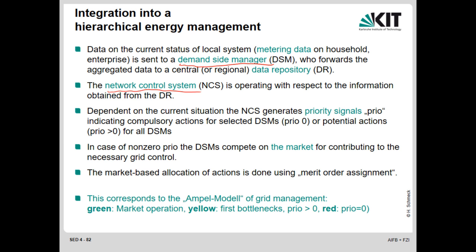A demand side manager needs information on what kind of demand management is necessary in the moment, and what kind of opportunities are on the market to sell a surplus of power or to sell flexibility. And it means that you need a combination of markets, demand side managers, and network control systems, like the distribution system operator, which has to be able to communicate with the demand side manager such that they actually provide the appropriate flexibility whenever it's necessary.